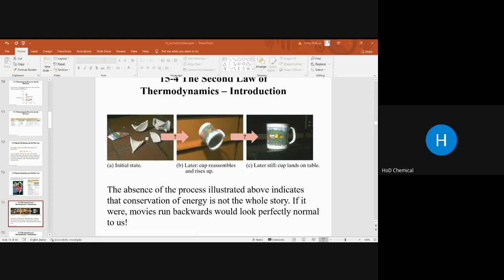This is the steam engine, reciprocating type. For the high temperature, the boiler is used, and for the low temperature, water is used. The water is pumped to the boiler to make steam. The heat input converts the water into steam, which drives the piston, and the piston takes the work. The steam is then condensed by the condenser and pumped back to the boiler.